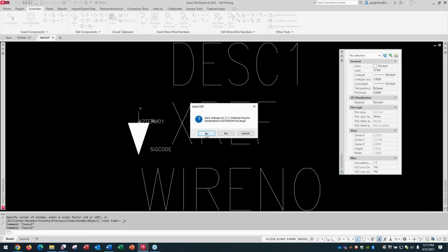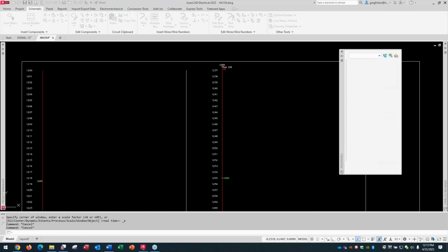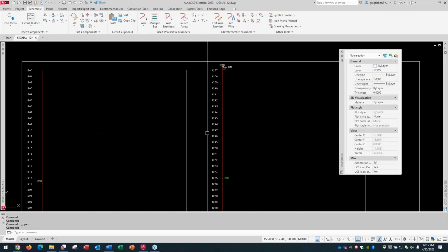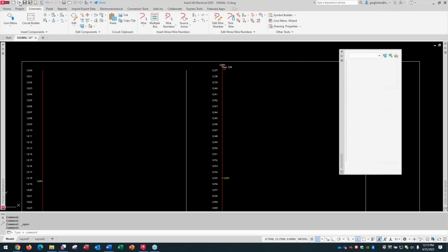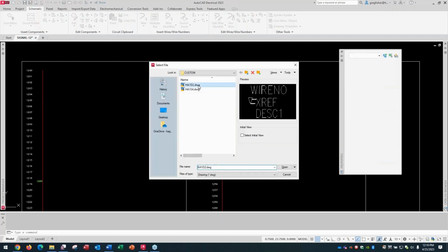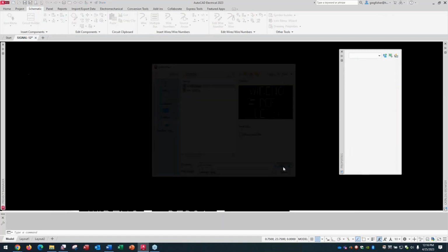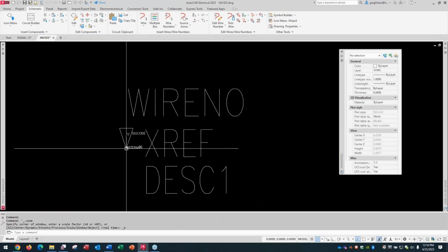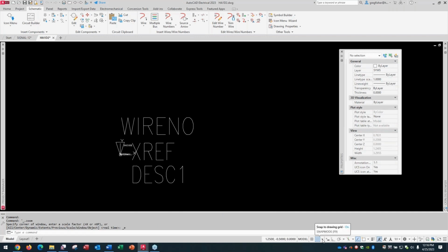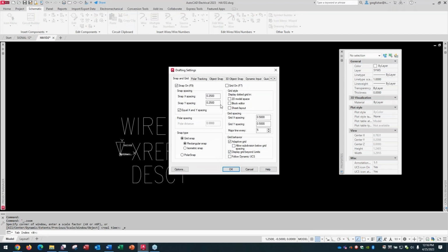Keep in mind the whole time, it's the same symbol name as what came out of the library, what came out of the box. Now I'm going to open up the destination. And you can do the same thing for the destination symbol: change the graphics, make the attributes invisible, change their justifications, change their height, change their position, do whatever you want to do with it.